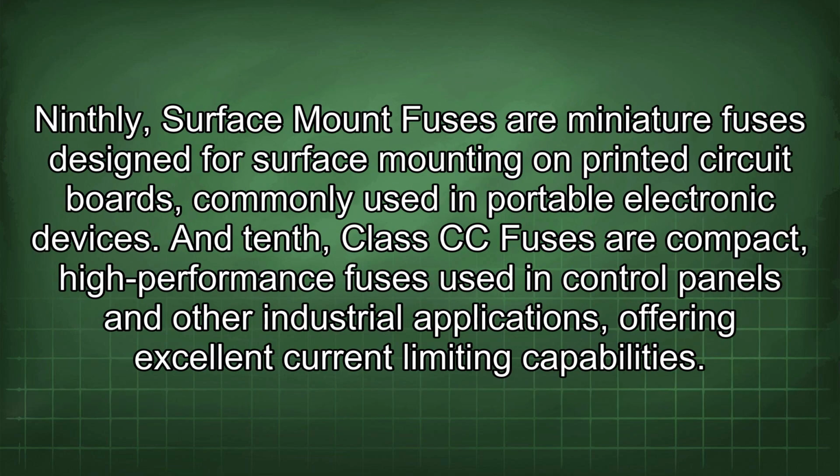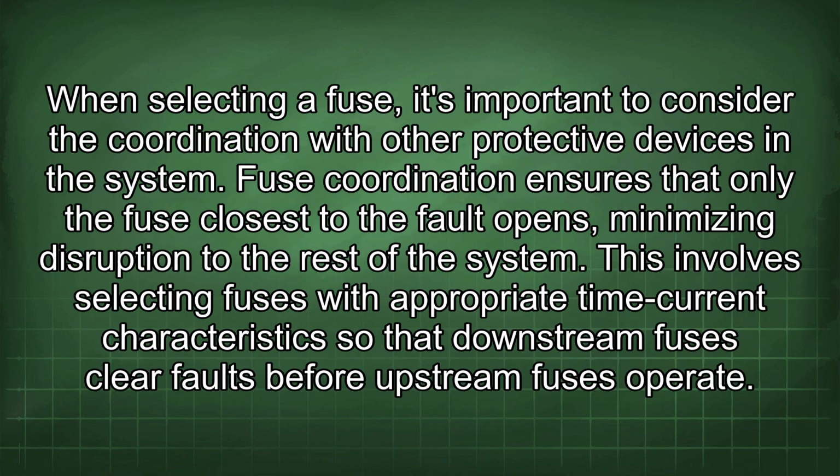Ninthly, surface mount fuses are miniature fuses designed for surface mounting on printed circuit boards, commonly used in portable electronic devices. And tenthly, Class CC fuses are compact, high-performance fuses used in control panels and other industrial applications, offering excellent current-limiting capabilities. When selecting a fuse, it's important to consider the coordination with other protective devices in the system.